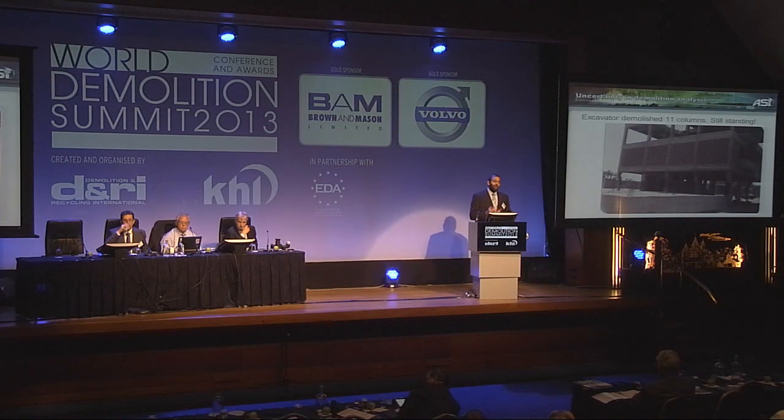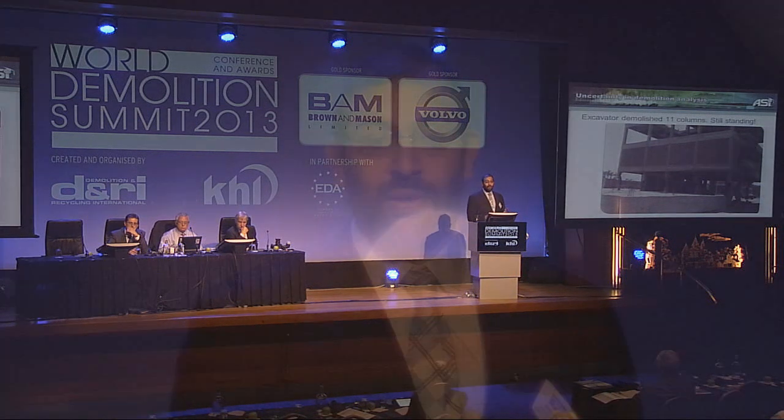But instead of discovering that after the fact, the idea is you do a simulation for the actual thing with all the non-structural weight, with everything that you have here, all the masonry walls, depending on how detailed you want this to be. But you do that prior to the analysis.